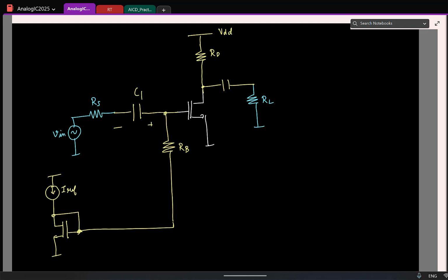That's all. What's wrong if we keep a DC voltage source? Oh, you are asking why don't we have this? Turns out in practice it is not available. You would have done all lab experiments, right? All signal sources have a common ground, and it has to be connected to the electrical ground, so that grounding is set. So in general all voltage sources typically are like this, unless you have that Duracell battery, where you can access both terminals. Otherwise it is always connected to the grid.